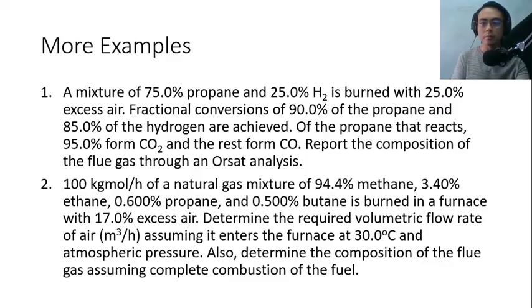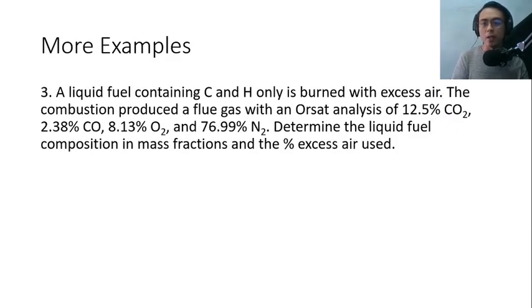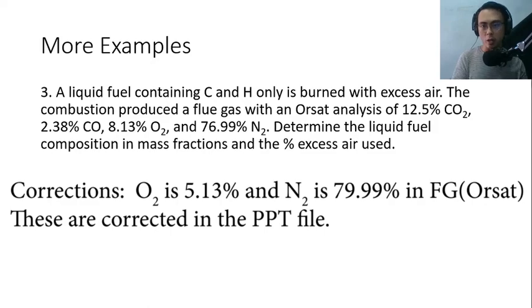Okay? And finally, a problem involving a liquid fuel. A liquid fuel containing carbon and hydrogen only is burned with excess air. You're given the Orsat analysis of your flue gas: CO2, CO, O2, and N2. Determine the liquid fuel composition in mass fractions and the percent excess air used.